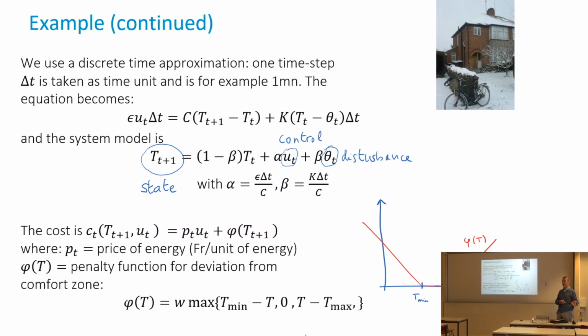As we have painfully seen in the past 2 weeks, constraints in an optimization problem lead to duality, Lagrange multipliers, all that kind of nasty things. So if we can remove them, that's the best. So we do it when the constraints are not hard. I mean, if we violate the temperature a bit, the world will not explode, right? If your set point is, let's say this is the UK, between 18 and 20, and your temperature gets to 20.1 degrees, there's no damage to the house or to the inhabitants. So the constraint is, in the nature of things, a desirable constraint, but not a hard constraint, right? So it's very appropriate in such cases to put a soft constraint. That's the red curve.